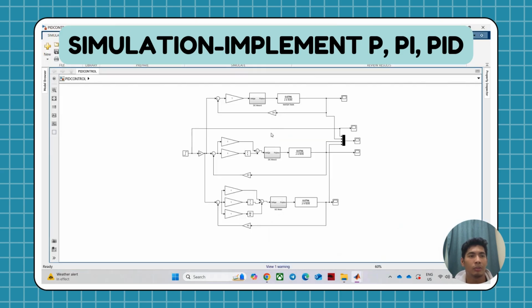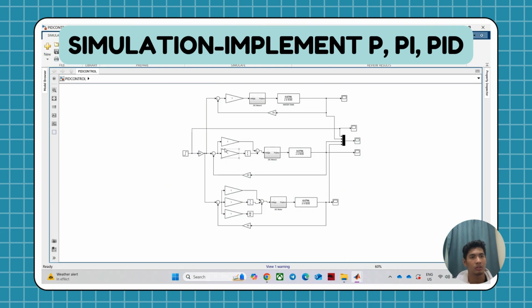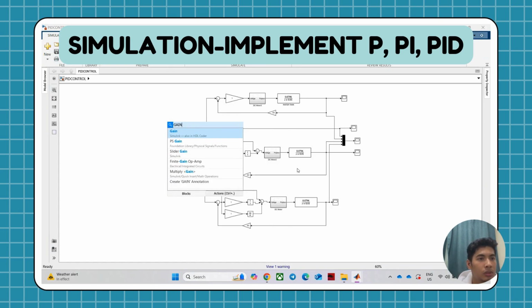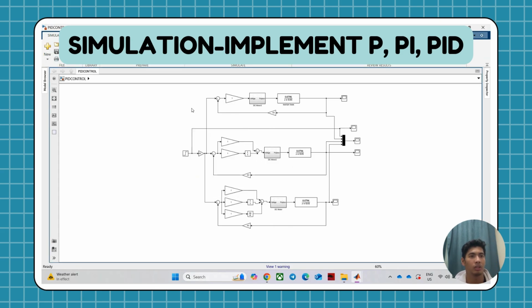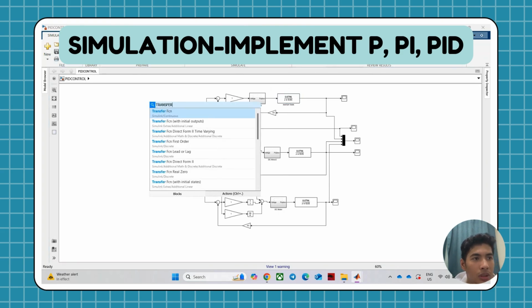Today I would like to present about implementing the PID controller. So this one is our full circuit. I just set up the circuit because I don't want to take time. So we just search gain to set up the PID controller, and then this one is the DC motor and water tank transfer function. So for the transfer function, we just right click and then search the transfer function.